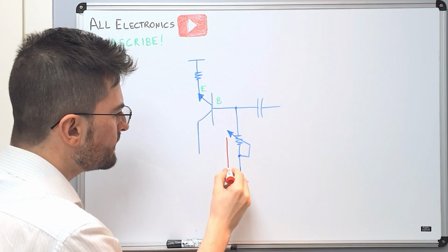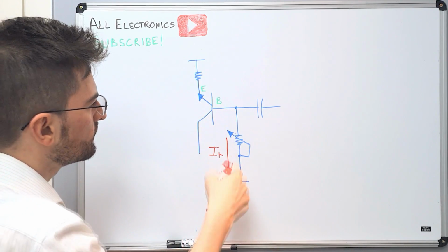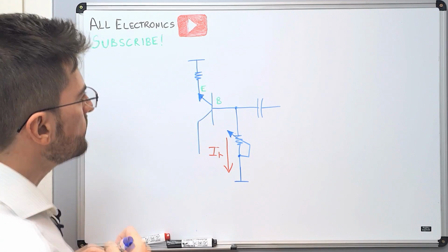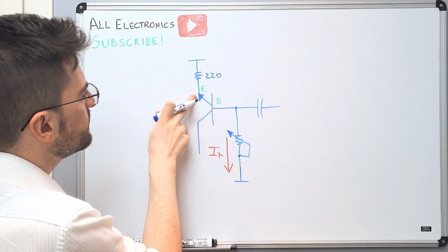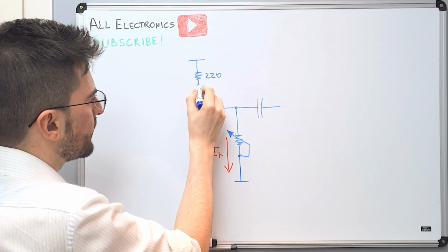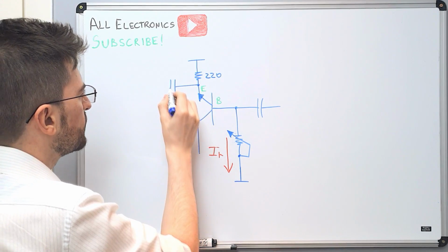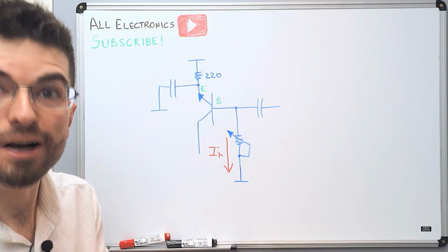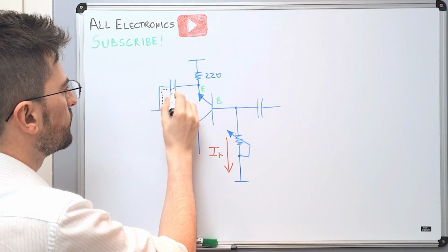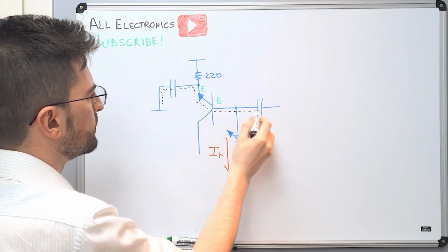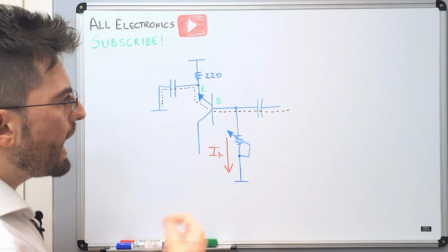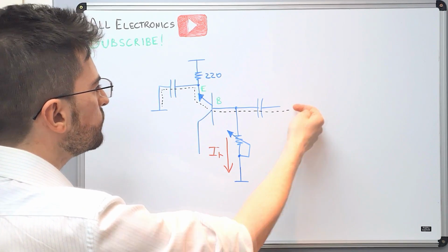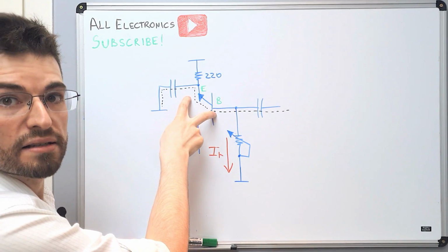This current is the reverse current being used to bias the junction, and this resistor here isolates the emitter from the VCC, and we can AC couple the emitter here to ground. So the AC path for the signal, here the noise is a signal, is this path here. You see? So when we measure the noise here, we are measuring exactly the noise over the reverse biased base-emitter